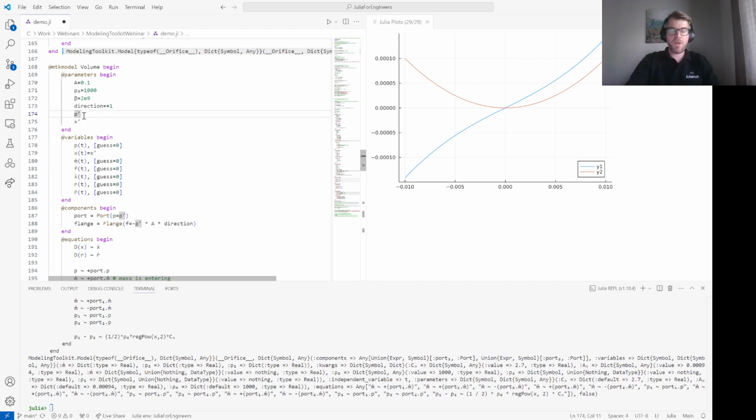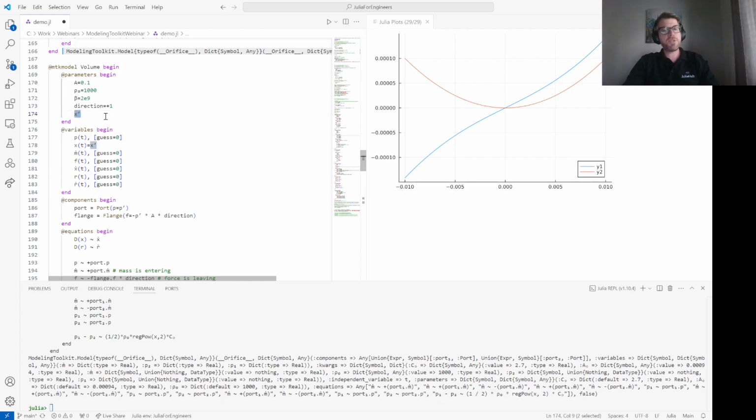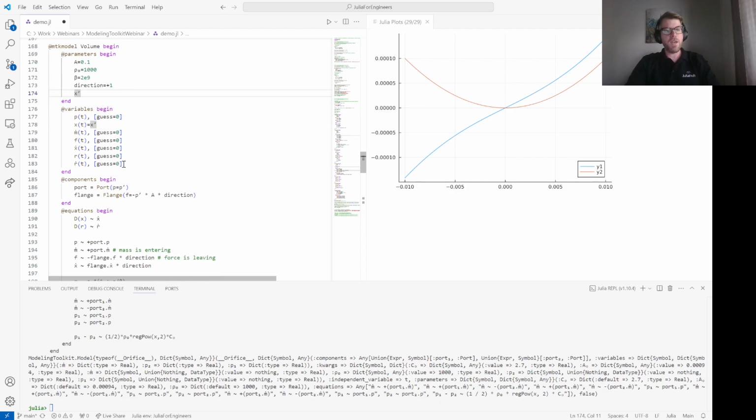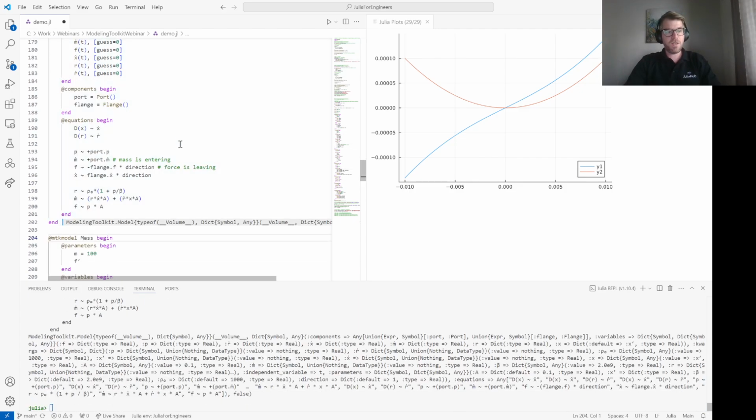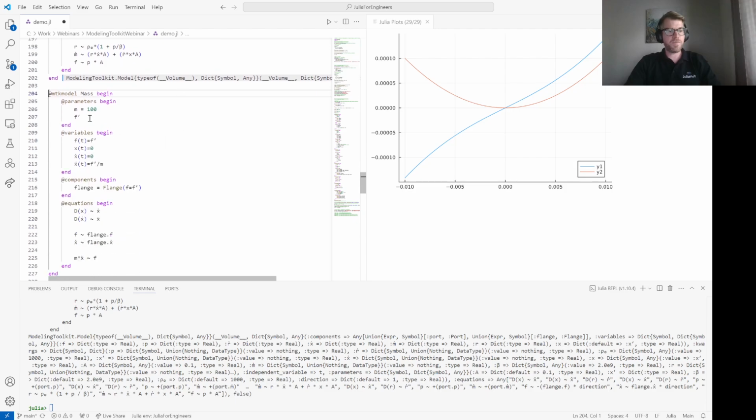So here we have a parameter that is specifying what is x at time zero, and we go ahead and assign it and create that initial equation. That's perfectly fine. That's exactly what we ought to be doing here. Nothing else we know. We don't know what the pressure is, the mass flow, the density, everything else we just guess at zero. Okay, so we can remove also this additional information that we were providing previously to fully constrain the problem. We no longer need to do that. That's all given to us for free now.